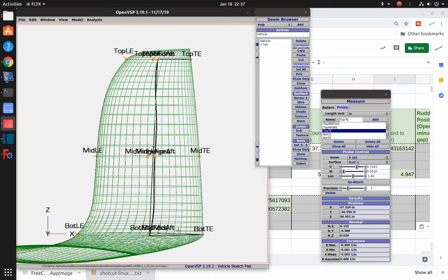And while we're here, let's talk about the top one again. For the top one, we're really close to the aft X. I looked at these fairly closely, and it looks like we're within about 10% of this little span between this fore and aft X. So what I think I'll do is calculate the span, multiply it by 0.1 to get 10%, and then add that to this fore X, and that'll give me pretty close to the X at the hinge.